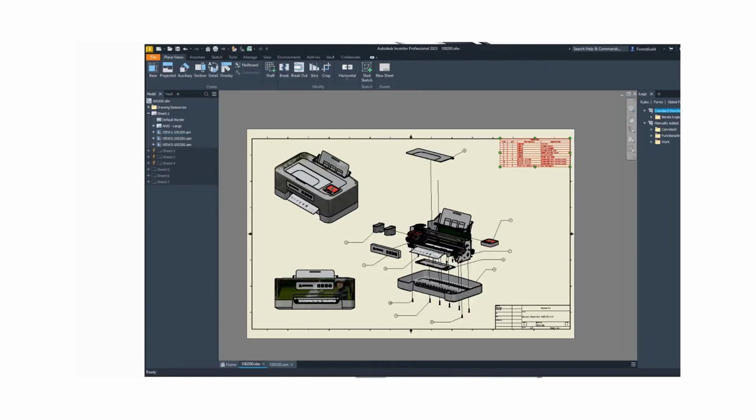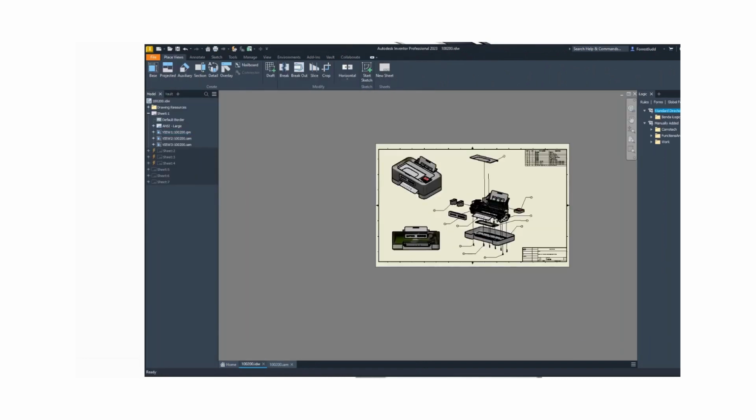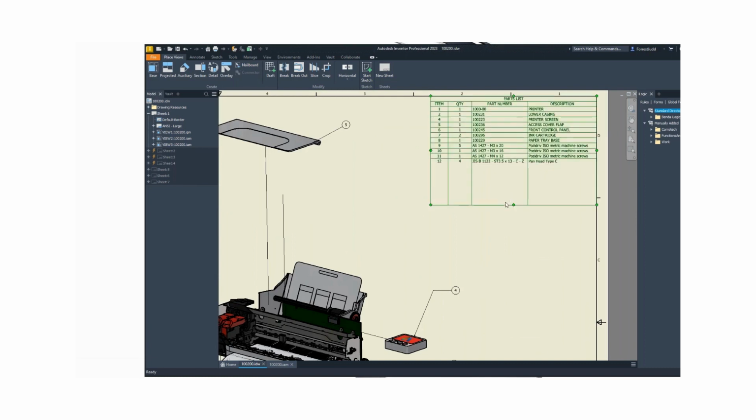Because you need Inventor and you very specifically have to know on the drawing, which sheet is it on? Is there only one parts list? Through the Inventor API, I should say, you can query the drawing and find parts lists and get this data out. And I have done that before. I would say generally that's pretty rare, but doable.